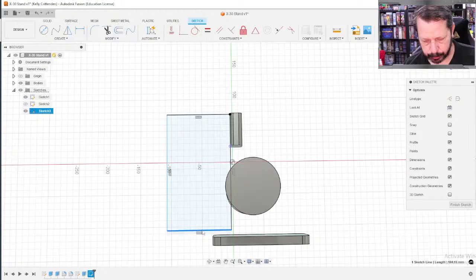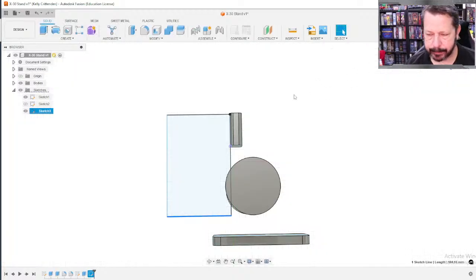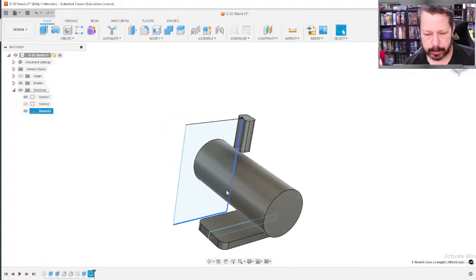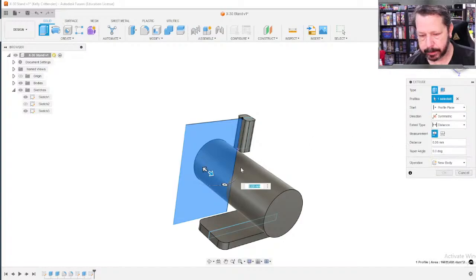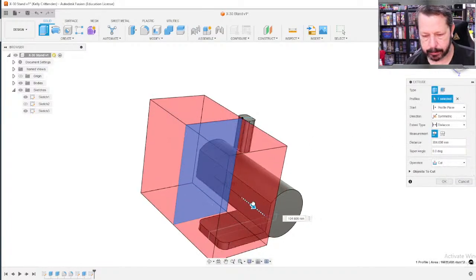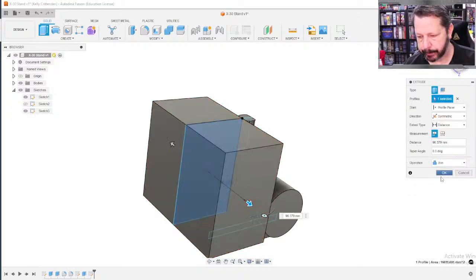It might need some room to do something down there, so actually, why don't we make it tangent with our circle, or close to tangent with our circle. All right, so that'll work, I believe. And then let's extrude that symmetric and just pull it out, something like that. Oh, but we want to join.